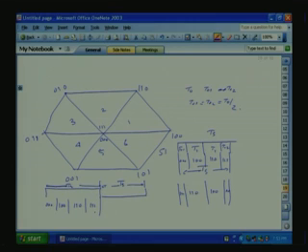Then the next sampling interval starts with 1 1 1, first T0, then 1 1 0, then 1 0 0, then the last zero, 0 0 0. So the sequence is T01, T1, T2, T02. Now here it will be T02, T2, T1, T01. This way it will go, and that will ensure minimum inverter switching.